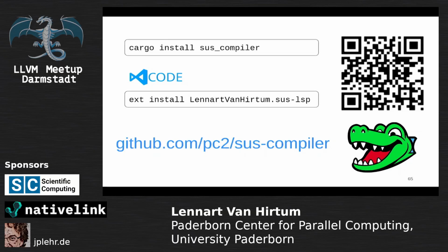So right now in the standard library, we have a bunch of modules, kind of like with Rust unsafe code, to get around the type checker where needed. So we have a cross-domain module where we can cross signals from one domain to another. This is looking forward to clock domain crossings. We also have a latency offset module to offset your latency value without adding registers.